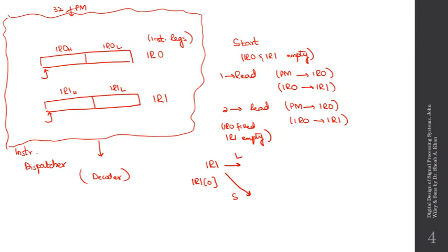If we get a long instruction, the data available in IR1 is to be forwarded. By forwarding, I mean the whole 32 bits have to be sent to a decoder. But in case of a short instruction, things will become a little difficult. Let's just complete the long instruction, then we'll move on to the short instruction.